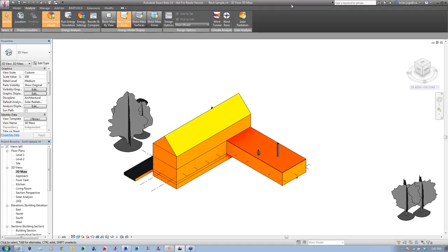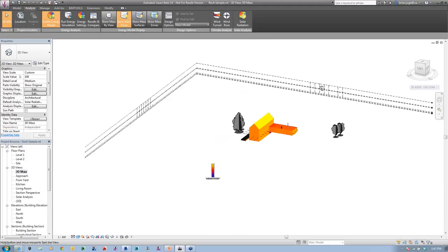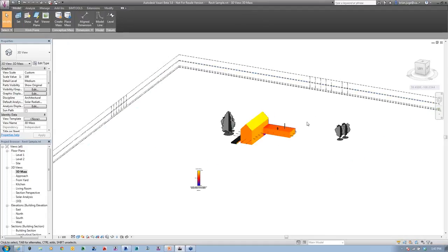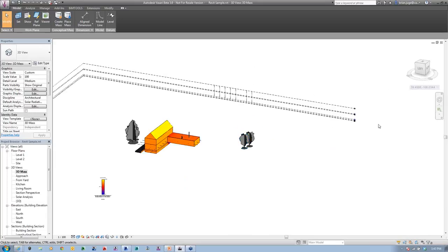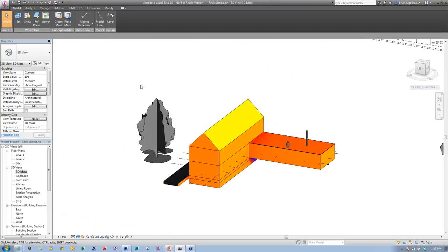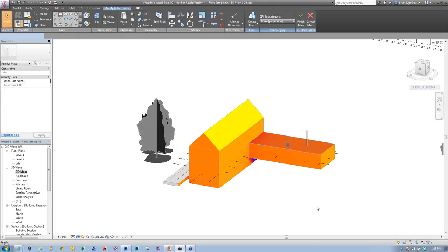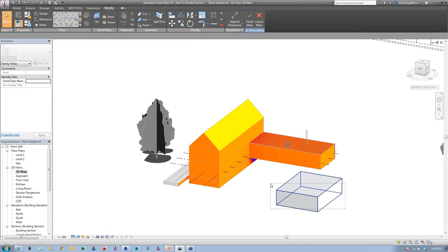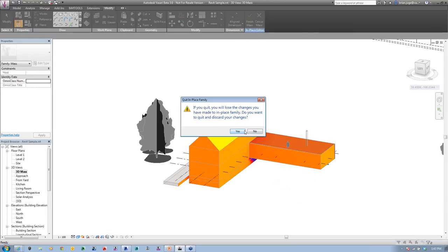They're on version 3.0 right now. And you can go in and build different masses in here. So here I have a building. Actually took a Revit model. These save as Revit files or .rvt files. But we can go in here and quickly mass our building out. So here I've got a building that has already been massed out, and I've been running some other stuff in here. But we have levels that we can drop in at different heights in here. Or other data, I'll get to that in a little bit. But just by simply going in and creating a mass, just like we would in any other project, I can go and design that. Come inside, create the forms, and create solid forms just like you would in Revit. So it's nothing different or new in here. It's the same process. It is the exact same thing as Revit, and again saves as a .rvt file.